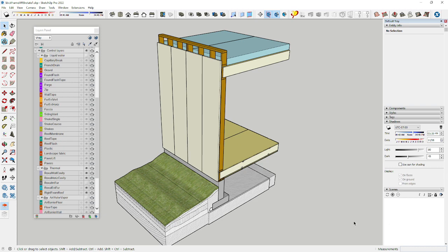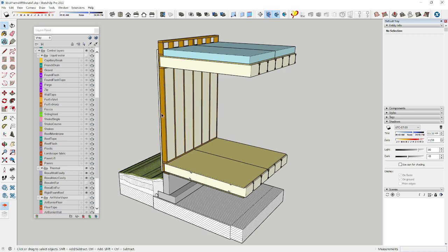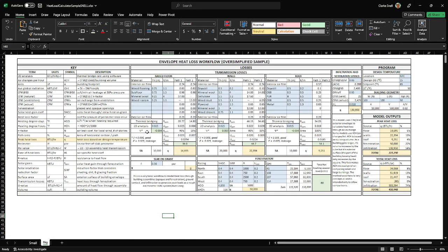So if we're going to be really accurate, or we don't have insulation covering the outside, we need to calculate what's called our thermal bridge psi value, which is just the total amount of heat we're losing through those bridges. There's a way of doing that by hand. It's usually done with a program called Therm that a lot of people use, where you bring in a drawing and you apply the different materials to the drawing, and it calculates it itself. All I'm doing here is making the point that this value here is not accurate, and that we actually need to do a thermal bridging analysis.